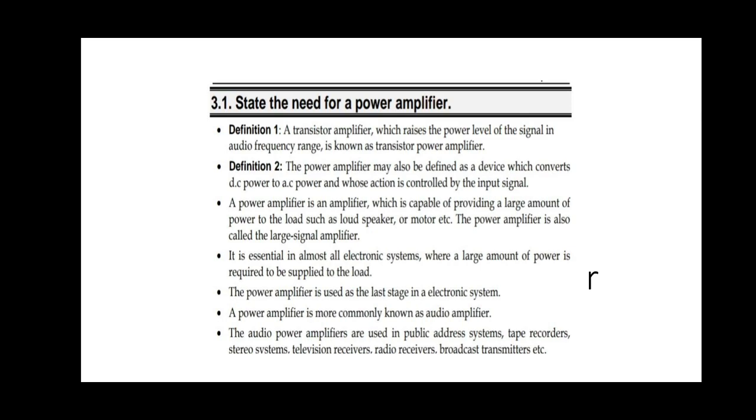In series, input impedance is increased; in shunt, input impedance is decreased. So for voltage series, the output impedance: voltage means voltage sample, so output impedance is decreased for voltage sample, and for a current sample the output impedance increases.